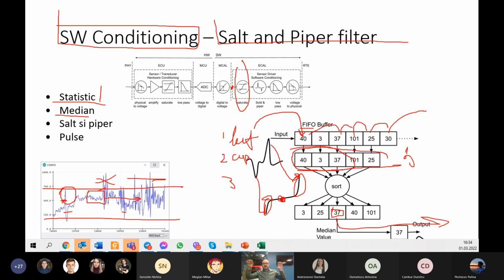So just keep a stream, take a copy, sort it, take the middle. That's all. So here we'll have analog read, push to the buffer, get a copy, sort it, and you will see that you will have all those libraries, except maybe the FIFO buffer. But you will have those libraries always on. By the way, even the buffer, you can implement by a copy of shifted values. So let's go further.